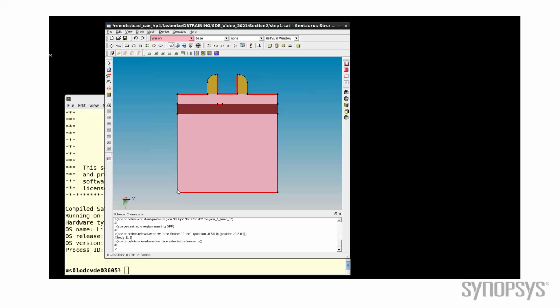The placement of an analytical profile is performed in two steps. First step defines the baseline, and the second step defines the properties of the profile itself. The baseline serves as the reference point for the depth of the peak position and determines the lateral extent of the profile. We are going to define a total of 4 Gaussian doping profiles, 2 for source drain and 2 for the extension regions.